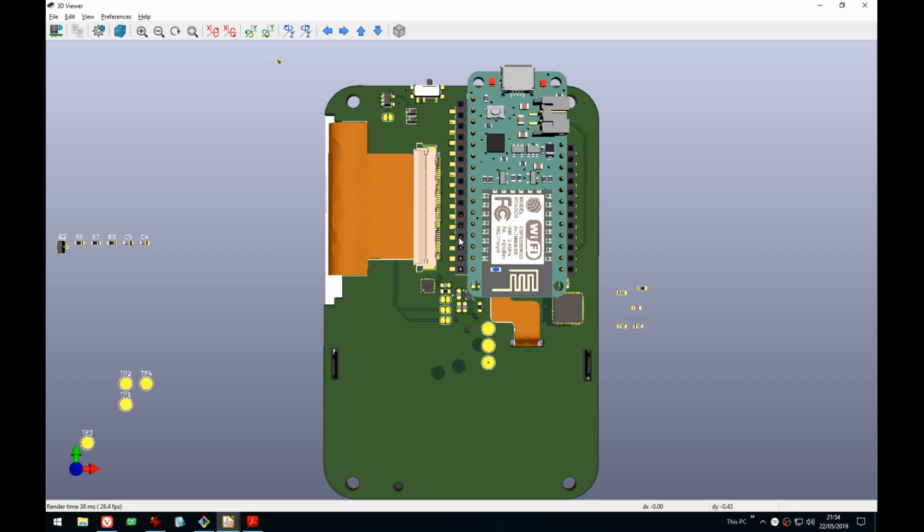Most of this can be hand assembled by someone with medium skills. If you're used to 0805 and QFPs, you might have some problems here. But if you know how to solder a QFN, you should be good with most of these things.